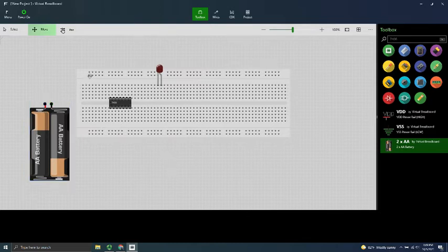So remember I said that this whole row up here could be ground, and the next one here could be power. Same thing down here. I can do this whole one as ground and the next one as power. When you get these boards and they're color coded, the one to the far right is normally the ground. It'll be blue. There'll be a blue line all the way across showing it's continuous, and there'll be a red line on this side showing that these are all connected. So you normally want to put the red to the power and then the blue to the ground. Same thing on this side. The ground's going to be there and the power is going to be on this side facing down.